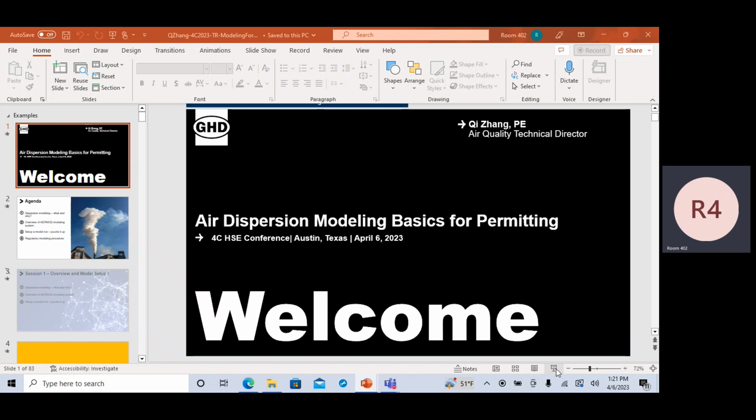In some cases, 0.2 or 0.1 really underestimates NO2. So now the EPA has put a minimum conversion ratio of 0.5 in the model. If you don't select your own ratio, AERMOD will assume a minimum of 0.5. It will not go further down. So that's basically ARM2.